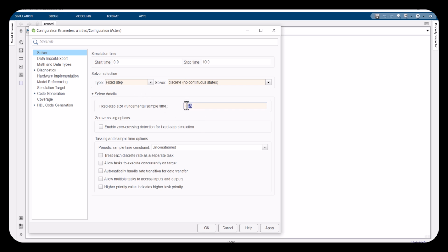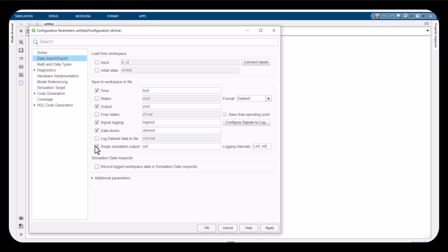So it is better that you define a fixed rate rather than a different value at each instant. Since all simulation should be real-life applicable, we're going to directly use discrete with no continuous states, and I'll untick this and make it an array for future references, and that's it. These are the two settings.